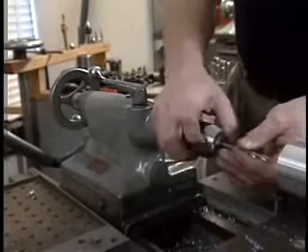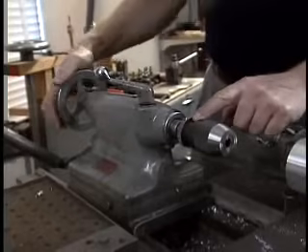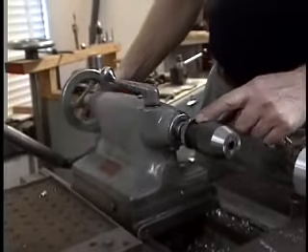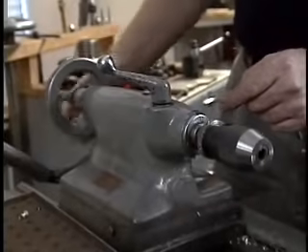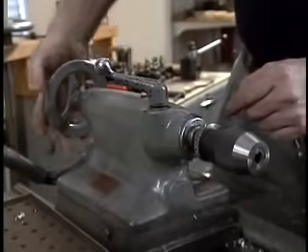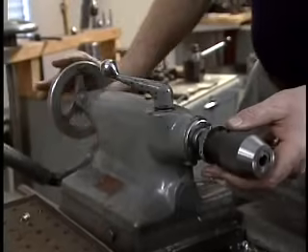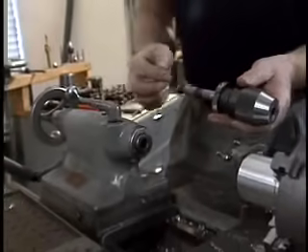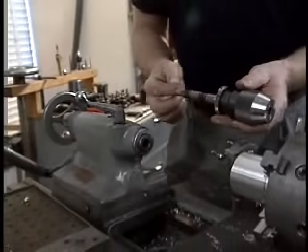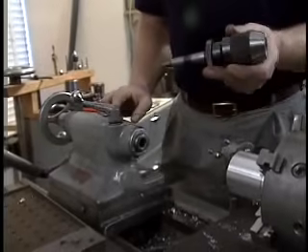After you've finished drilling the hole, the drill chuck can be removed by drawing the tailstock back all the way until it stops. Turn the handle back a little further, and a pin inside the tailstock will press the taper out of the tailstock and release the chuck.